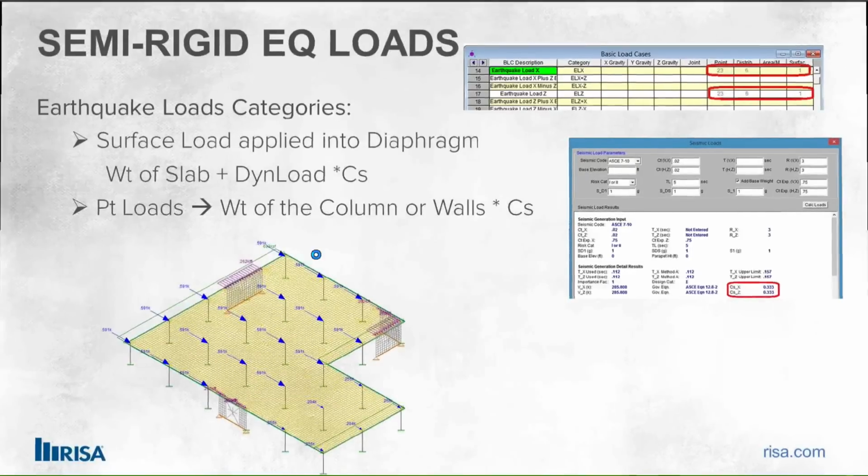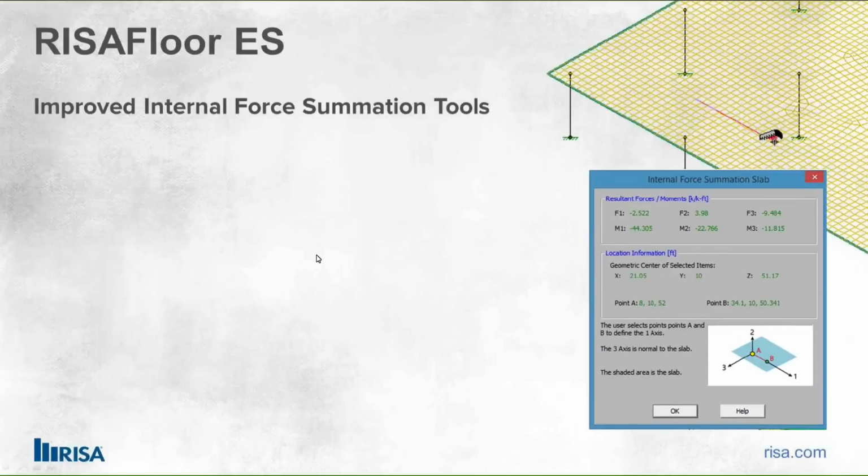The other thing is that we added some internal force summation tools. In RISA-3D, the program isn't going to design your rebar, but you can use this tool quick and easy to find your forces and design the reinforcement for yourself. We always had an internal force summation tool, but it went across the entire plane. That wouldn't help us too much because we want to find more of a localized picture of what's happening in the slab. So we've added this tool that will find the plate forces right directly inside of RISA-3D.